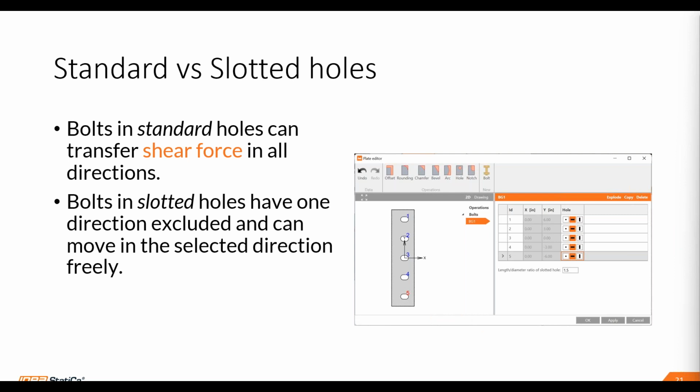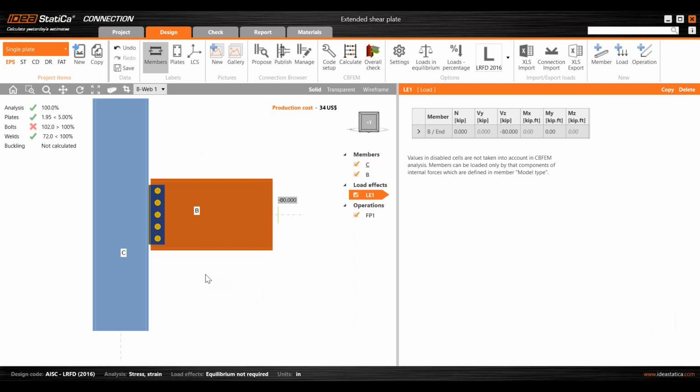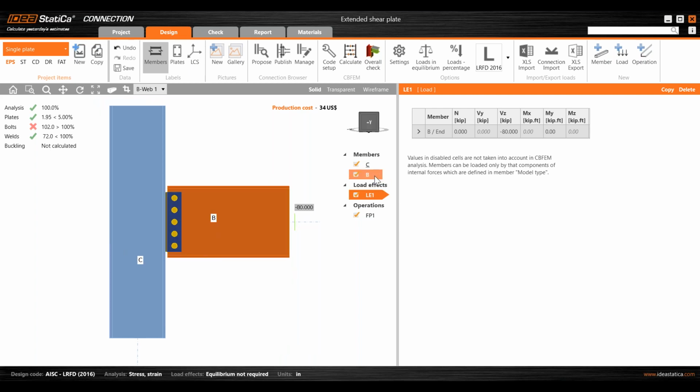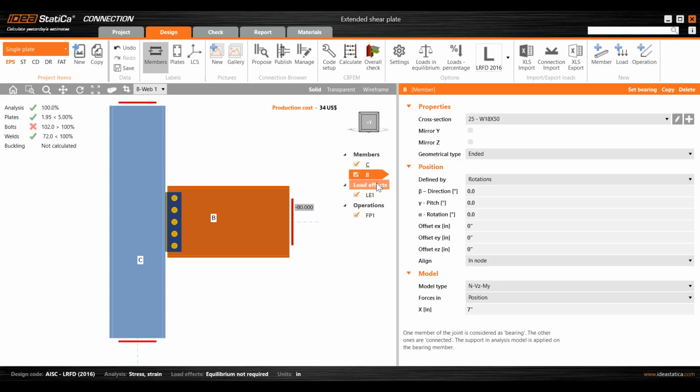When I have a connection with both shear and moments, how do I stop the shear weld from adding to the moment of the connection? So I'm guessing the best way, if you want to have the shear only going down, for example, in the shear plate without adding to the moment, would be playing with the point of zero moments and where you actually want to set the location where the vertical shear load is applied.